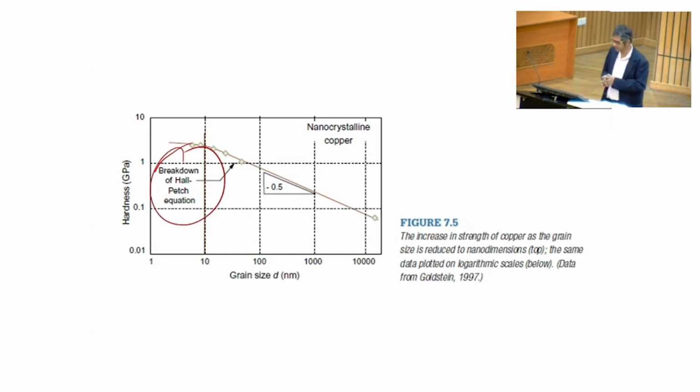So what did I discuss in today's lecture? Let us compile. So I told you that the tensile test is the most important test to determine the mechanical behavior of material, correct? Then I talked about multi-grain materials, how defects can pile up at the grain boundaries and the grain boundary can act as an obstacle, correct? Then I derived this Hall-Petch equation, and finally I showed you why the equation breaks down. So that's for today.